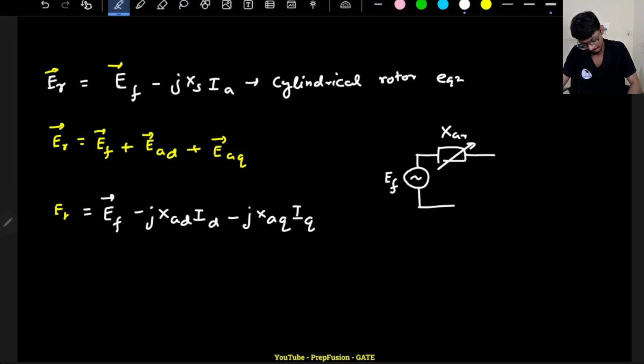Okay, then this point is known as the, after removing XAR due to the armature reaction, I get my resultant EMF, and then we consider our RA and our leakage reactance XL, right? This will always be there no matter what.